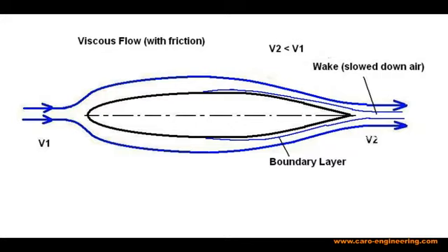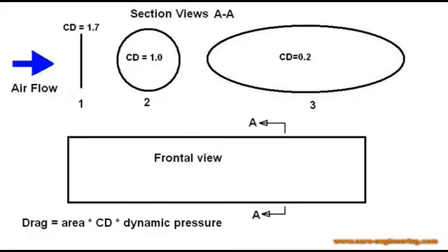There are several different types of drag, which I want to present in some detail because they require different methods to minimize them. The easiest one to understand is form drag. Every object that is moving through the air has to push that air out of the way. How much drag an object produces depends on airspeed, its cross-section, and its drag coefficient. The drag coefficient CD is a number that factors in the shape of the object because that has a big influence on how high the drag is. It quantifies the losses and the size of the wake.